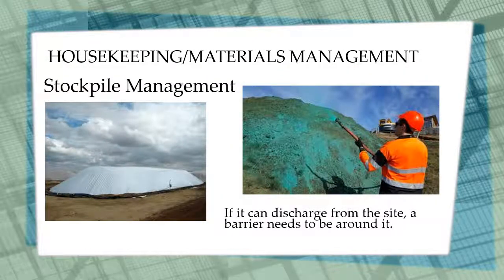Next is stockpile management. If a stockpile is going to be sitting unused for 14 days, it must be stabilized. That can be done through a variety of methods, either covering it with a tarp, mulching it, putting on temporary seeding, applying straw and a tackifier.